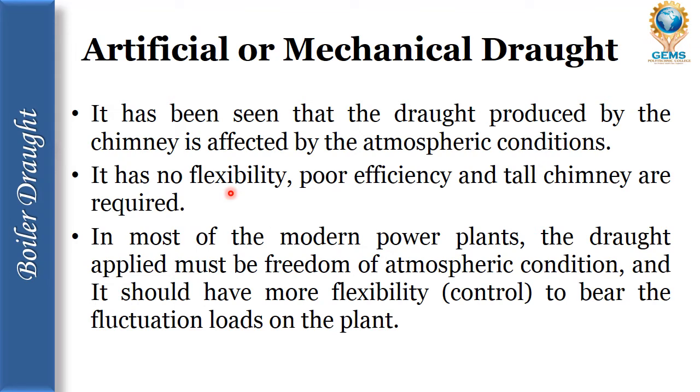Now let's see about the artificial or mechanical draft. It has been seen that the draft produced by the chimney is affected by the atmospheric conditions. So it has no flexibility, poor efficiency, and a tall chimney is required. In most modern power plants, the draft applied must be free of atmospheric conditions, and it should have more flexibility or control to bear the fluctuating loads on the plant.